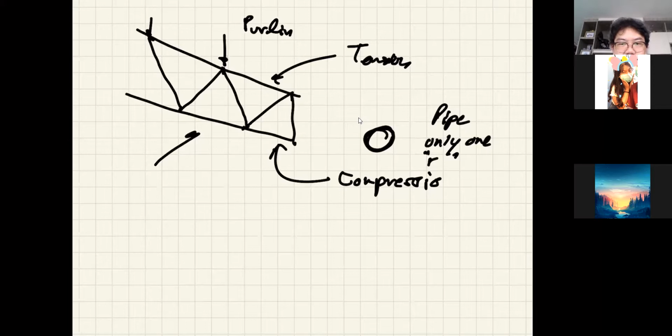And you see, this is no more than what you have done with statics. The analysis of the truss is the same. The additional knowledge that you should have here is the treatment of the unbraced length. Okay. So is there any question?